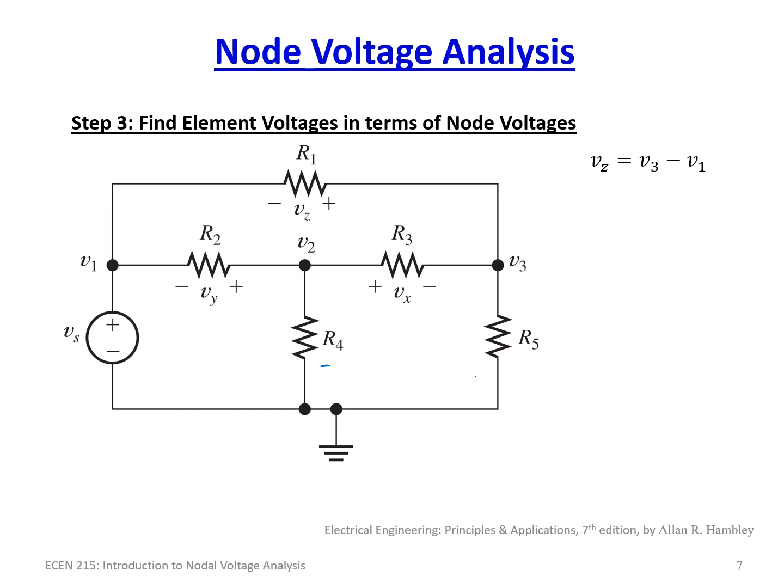VY is V2 minus V1, in other words, the voltage drop across this resistor. VX, which is the voltage drop across R3, is simply V2 minus V3. And the voltage drops across R4 and R5 are simply V2 and V3 correspondingly. So we went ahead and wrote our equations.